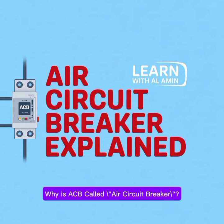Why is ACB called air circuit breaker? When the breaker opens under fault condition, an electric arc is produced between the contacts in ACB. This arc is extinguished using atmospheric air. That's why it is called air circuit breaker.